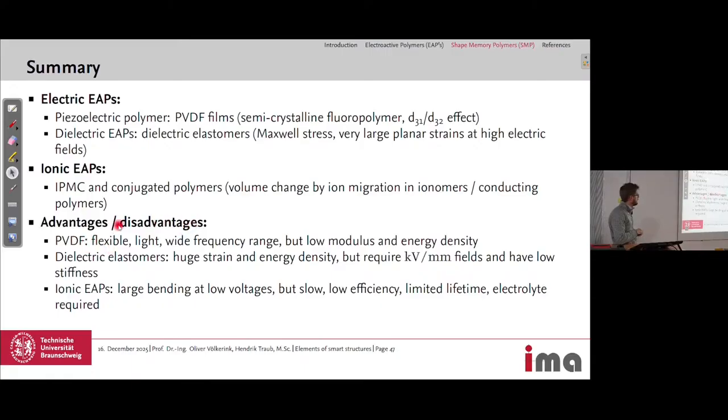And if we look at advantages or disadvantages, PVDF is flexible, light, has a wide frequency range, but low modulus and energy density. The dielectric elastomers have huge strains and also high energy densities, but also require high fields and have low stiffness. So again, large displacements possible, but only low forces.